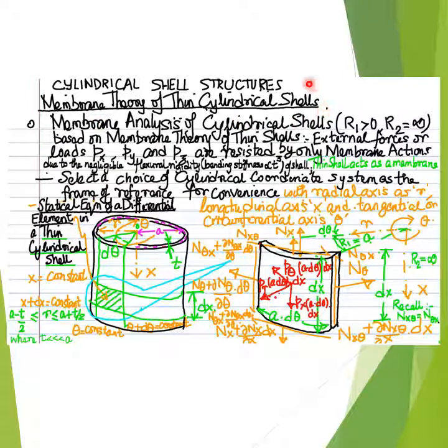The flexural rigidity or the bending stiffness of the shell being negligible on account of being a thin shell, the shell is unable to resist any out of plane or plate actions.